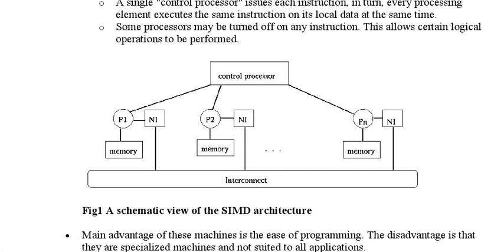For example, the contents of this for loop will be routed to the different processing elements so that they can be executed in parallel in the same clock cycle. And you will have a scalar processor which will execute this standalone scalar instruction. In our example, it is int i equals 100.